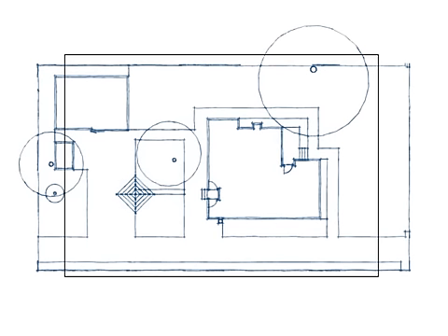If we do the same thing for section and paper width, we get a scale of 1 to 75. If we drew the whole section onto our piece of paper at a scale of 1 to 75, then the section would fit widthwise, but would extend off the page in the lengthwise dimension. For this reason, you should always use the bigger number when choosing what scale to draw your site plan at. Site plans should be drawn at a standard scale, usually 1 to 100 or 1 to 200.